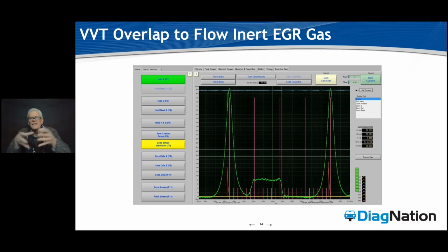Listen, when we have a vehicle that's 40, 50, 80,000 miles, the rings have started to degrade, and we're now having a serious drop in compression. And when I say serious, in the baseline strategy, we just did one last week online using carbon removal chemistry for the rings, and pulled back an average of 36 pounds per cylinder. 36 pounds per cylinder, guys. When you have customers that are coming in talking about lack of power and you can't find the problem, you need to start checking that compression.